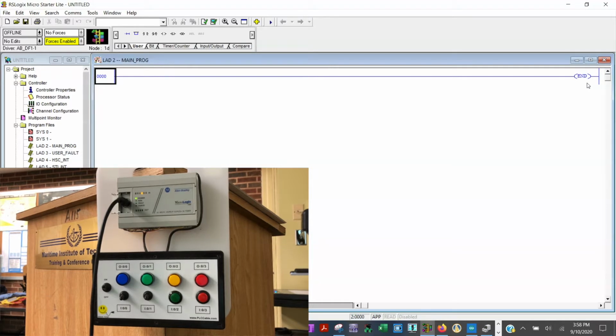It scans the program down, and it collects all the inputs, right? And then it gets to the end, and the end tells it go back up to the top again. So it goes back up to the top, and now it knows all the inputs, and if the inputs are positive so that your output is energized, then it's going to energize the output on the next scan. But these scans are happening 1,000 times a second, something like that. That's what this end rung is.